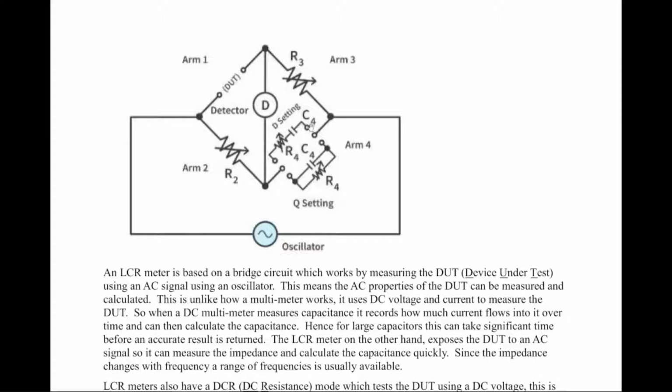It can be measuring capacitors with resistance in series. It can measure capacitance or an inductor with the resistance in parallel, and depending on all the values here, there's either going to be some current in either direction or none in the detection circuit here. And this thing is driven by an oscillator, and that is where the frequency thing comes in. Now you've seen me select 120 hertz, 1 kilohertz, 15 kilohertz, and what have you. That's the oscillator here.